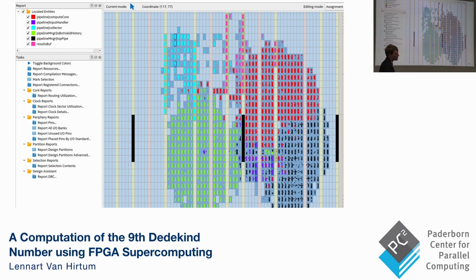On the FPGAs I use, they are M20K blocks, so 20 kilobit blocks. And then finally, we have these gray bars here in the middle. These are big multipliers, but I did not use them. Other people in my department use them quite a lot, but I had no use for them in this project.